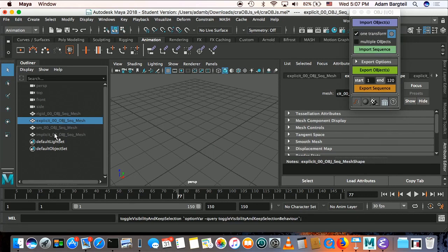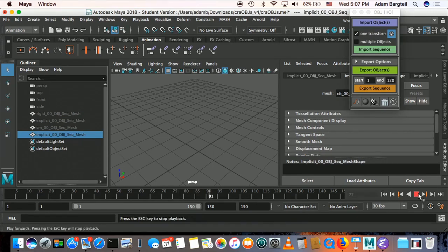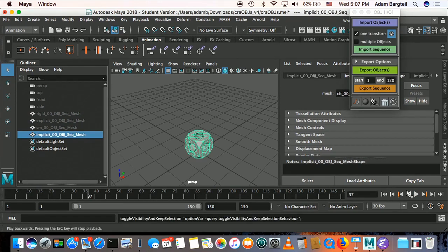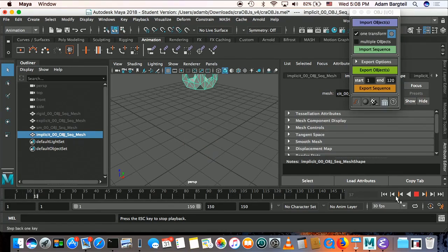And then with implicit integration, did it not? Okay. You'll see that things are much, much more damped, and that's just the artifact of linear and implicit Euler. In order to remain stable, it reduces the energy in the system. And so we don't get as nice a bounce, but you're much more likely to remain stable in most of the circumstances you're interested in. You also get less deformation. I mean, it almost looks rigid.